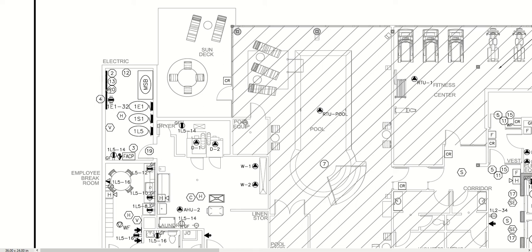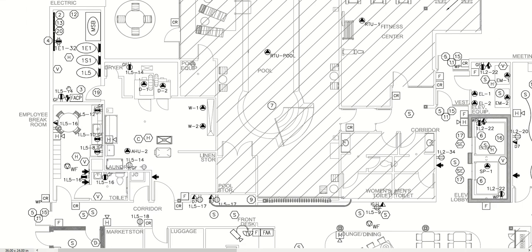And here we have our telephone backboard, so you can see we have an outlet on the wall for that, and then an outlet over here on the wall. And these are up at 46-inch height. We usually put them up high in the electrical rooms because they're usually plugging in hand tools if they're working in there. It's a little more convenient for them. And you can see they have the circuit tags just as the light fixture did. So this would be from panel 1E1, circuit position 32.